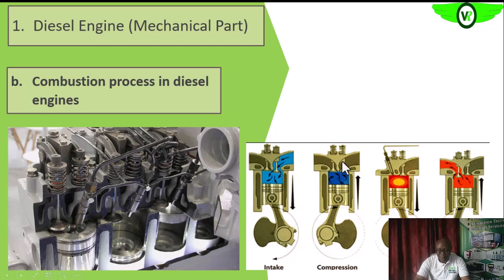At that time, this valve will have closed. Okay, the intake valve will have closed. And then as the piston is moving up, it's reducing the effective volume of the cylinder, and that will end up compressing the air that has been admitted into that cylinder. So it will compress it to the top dead center, where the pressure on the compressed air is highest.